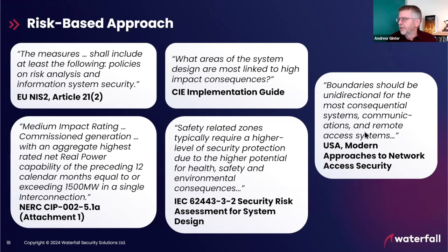And finally, in the remote access, again, the latest advice is saying on the OT side, for high consequence OT systems, your boundaries between networks should be unidirectional, hardware enforced one way. Nothing can get back into your high consequence systems. If you're going to use remote access, it has to be hardware enforced unidirectional remote access. This is the best advice out there. That's what I had for you.